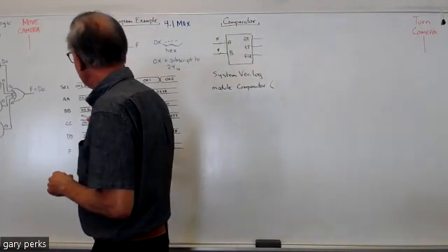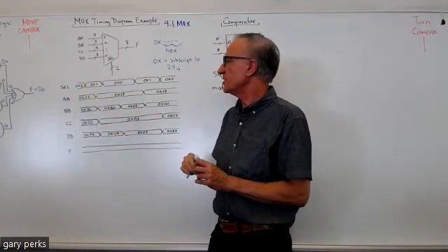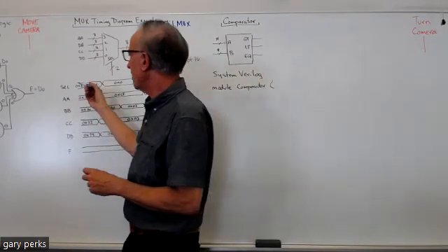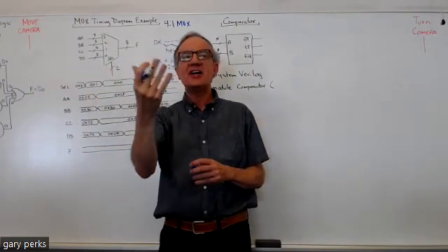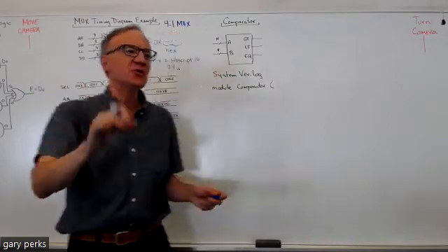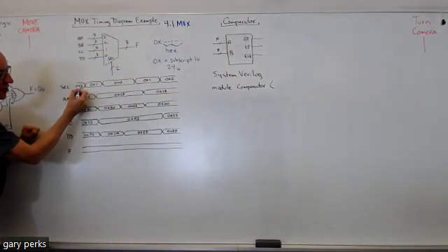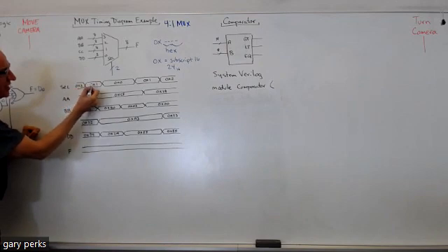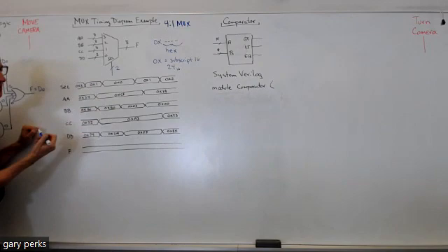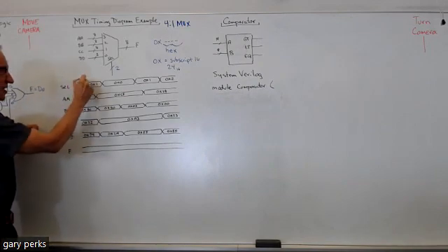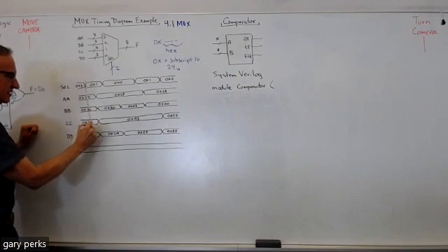All right, so let's figure out what this F output is. Just like we've done before in timing diagrams, you start at the left at t equals 0, and you have to evaluate every time there's a change in input. And that's what this hex is showing. This is changing from 3 hex to 1 hex, right? This is changing from 24 hex to CF hex. Okay, but let's draw a line here.